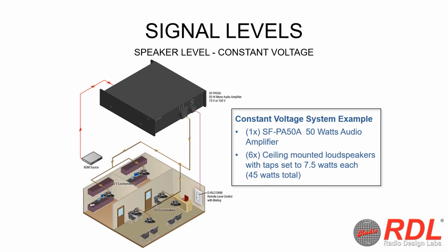Constant voltage amplifiers can support any number of speakers as long as the amplifier's maximum power or total wattage is not exceeded. These systems are ideal for voice and low-level music applications such as paging and background music.